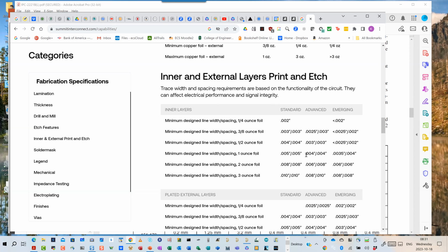So regardless of the fact that I only have digital voltage levels or 12 or 15 volt power levels for my analog power supplies, it doesn't really matter, because the fabricator is going to dictate to you what your minimum feature size and spacing is going to be from a manufacturability point of view. So to Vibe's question earlier about wanting to learn design for manufacturability, this is one of the key areas where many an engineer makes a mistake: they don't understand the manufacturing capabilities. And the IPC chart says you can do 2 mil clearances.